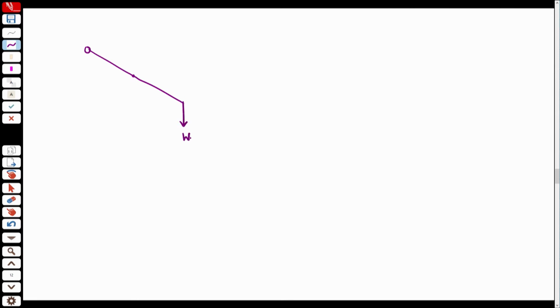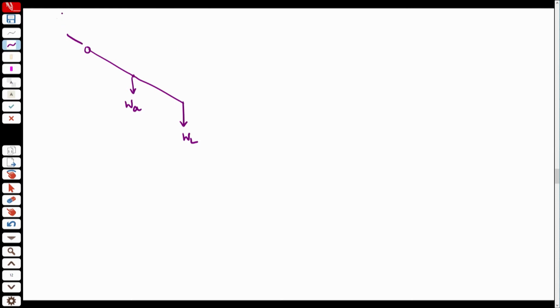So, I have WL, I have the weight of the arm. Now when you look at joint reaction forces, it is always a good idea to take the two perpendicular components, along the axis and perpendicular to the axis, because you are looking at the dislocating or stabilizing component and the other component. So, you can take this as J A, the axial component, and J N, the normal component.